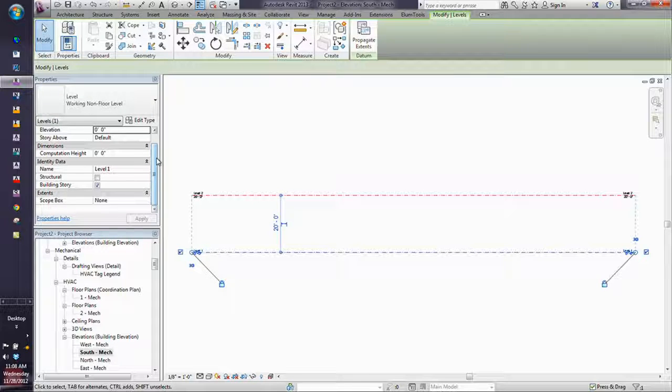And we actually changed their visibility for all of them so that they really jump out on the screen. So like that ceiling level in there that we're not going to define a view from, we went ahead and made it a completely different color. So as we copy monitor these, it's very clear which one we're supposed to use and which one we're not supposed to use. That made life a whole lot easier for everybody. Okay? Pretty slick?